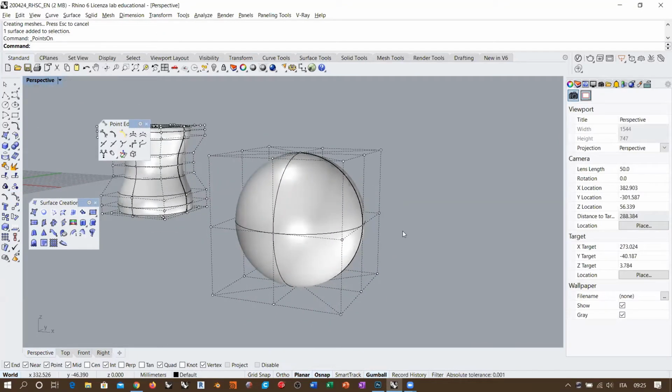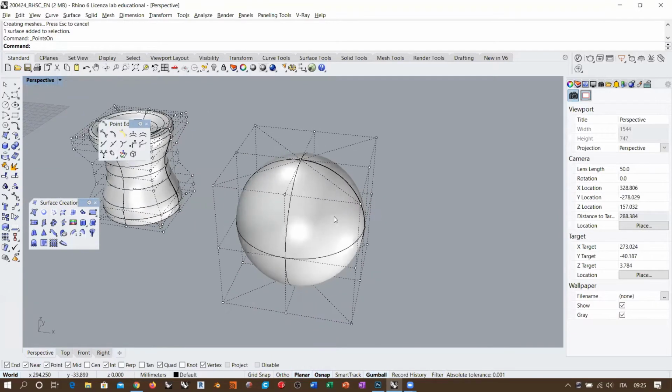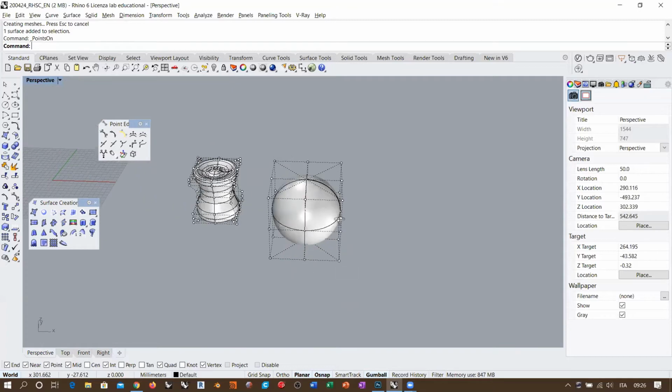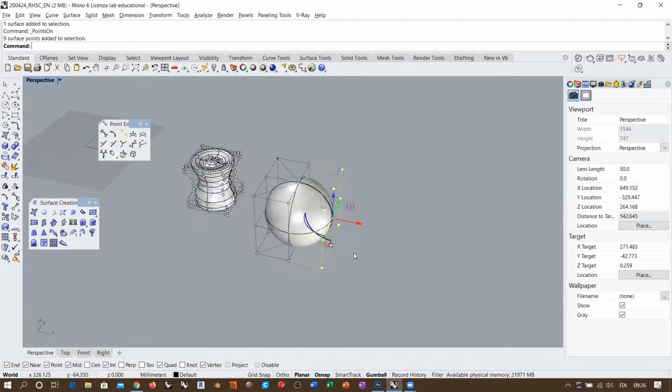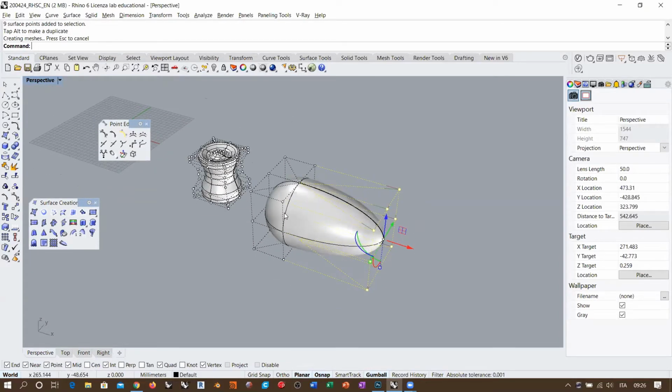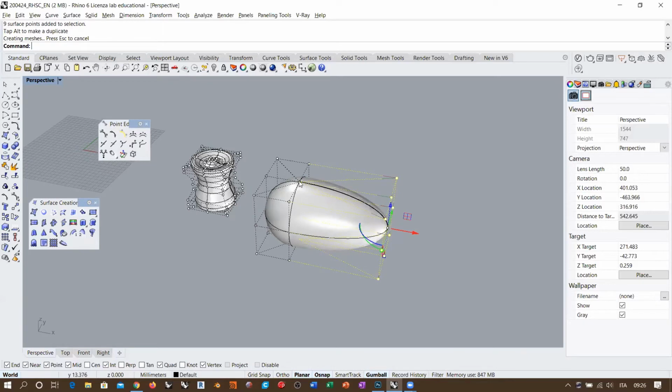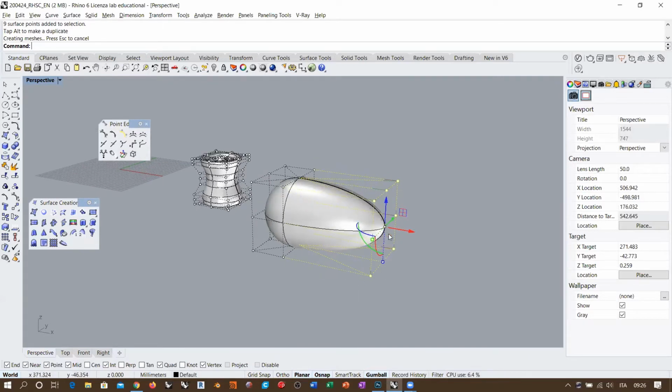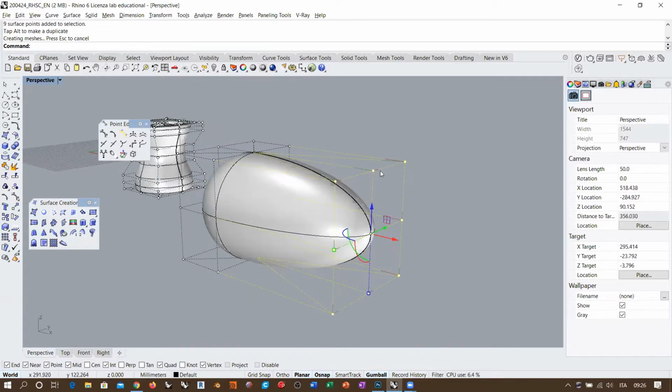Okay. So whatever operation I do on this sphere is going to produce some kind of crease, right? But if I select, for example, in this case, the whole plane of control points here, and I move it, I'm not creating any discontinuity because I'm not working with these points here individually. Okay, so the points that I have here are the kinks, and I cannot touch them. But I can touch the whole plane that contains the kink and keeps the tangency untouched.